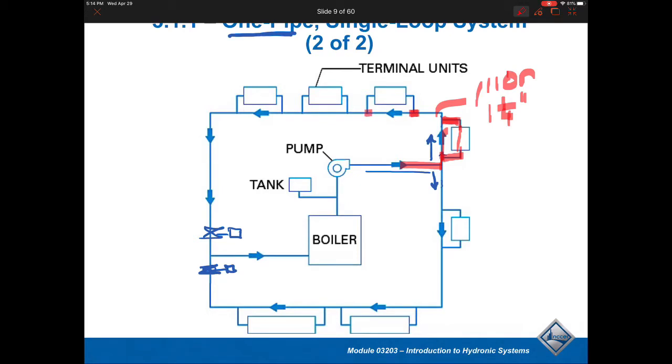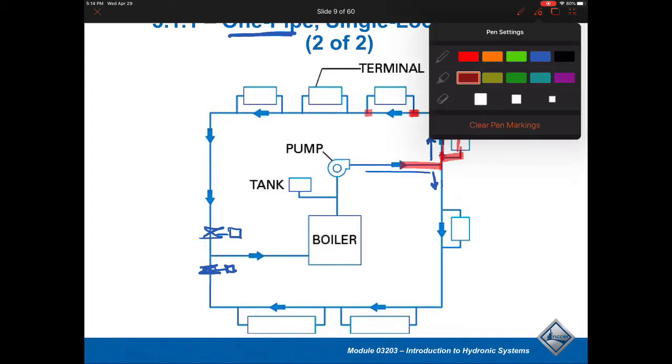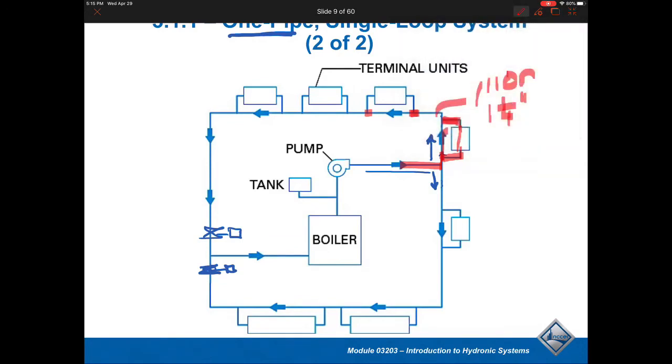That means you either have to have a monoflow tee, a one pipe fitting tee, here, or in both places. If you ever have to pipe those, or service an account that has one of those, you might want to watch for those little specialty rings. They basically have a section or part of that tee that has to be in between the terminal units.